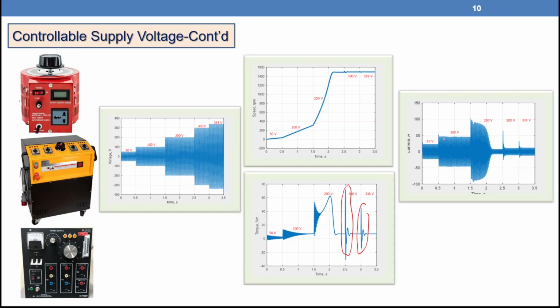Here we have, at 50 volt, this current. We increase the current gradually until this point, while the current for direct online, if you remember, has an envelope. Here we have something like 20 ampere at starting, while if we have direct online starting, we have something like 100 to 150.